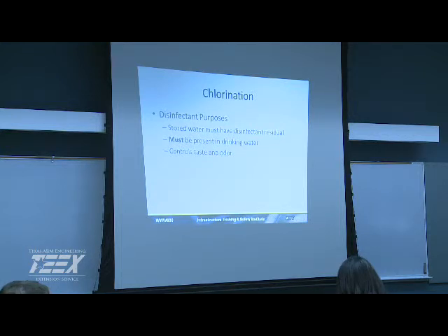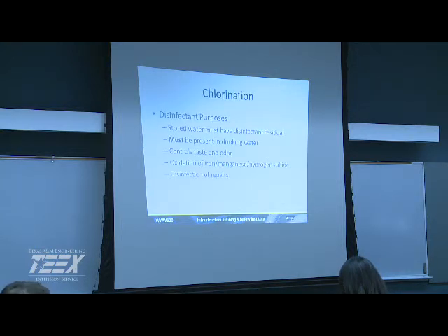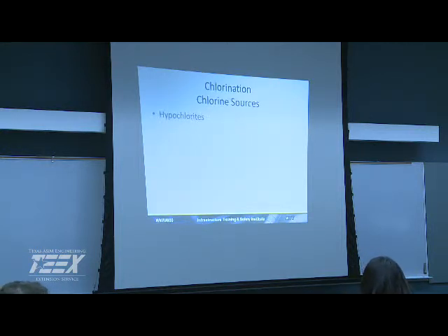That's why people are going to others like chlorine dioxide or ozone, depending on your source water, in the pretreatment portion to make sure that you're not building disinfection byproducts. Get rid of all that organics and other material you have: iron, manganese, and especially, in some groundwaters, high hydrogen sulfide. That's a good way to get rid of it also. And then if you're doing repairs, you have to be able to disinfect, and then flush well.